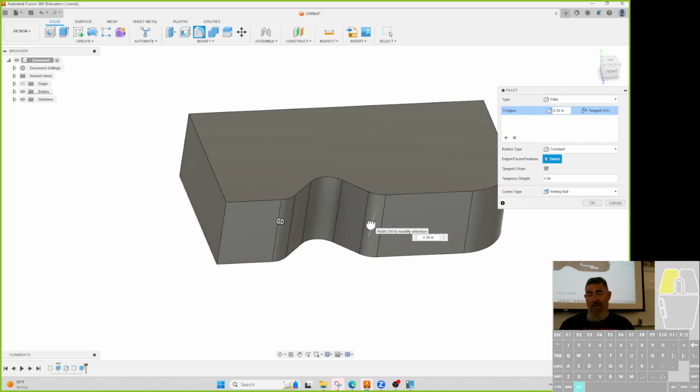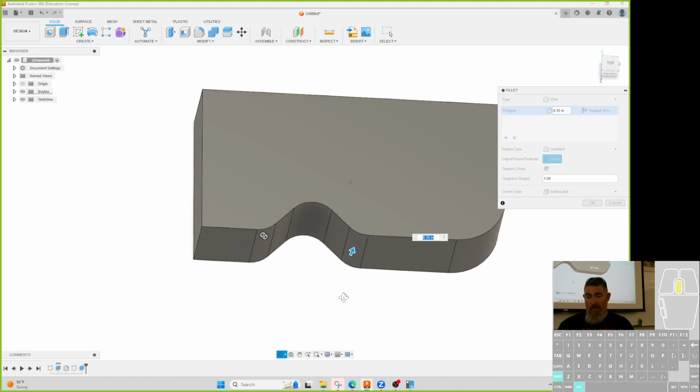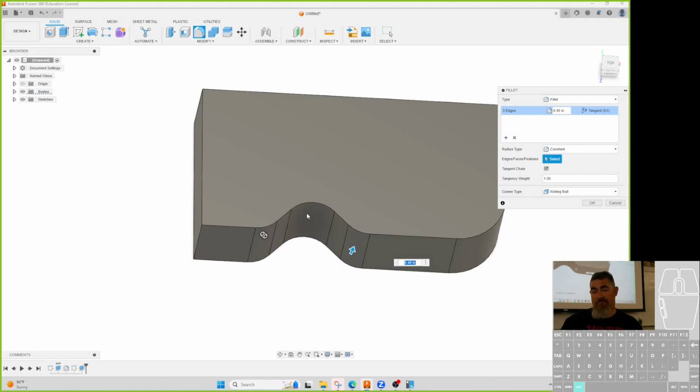And here, and you notice that the length of the curve is different, right? Same radius, but why is this curve a lot longer than that curve? Because it was originally a sharper angle? Yeah, more acute angle. It's got to make that same radius, it has to take out more of that piece, right? It has to take out more of that to keep that same radius tangent.